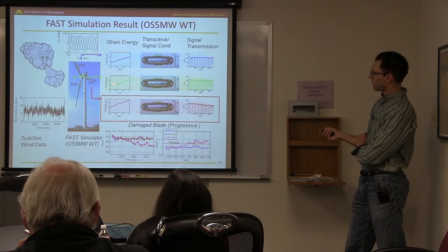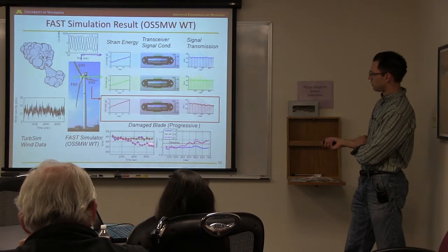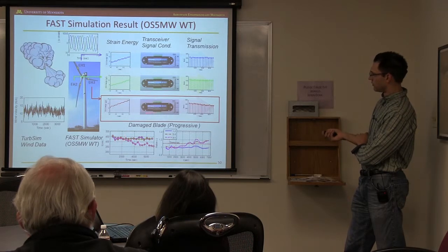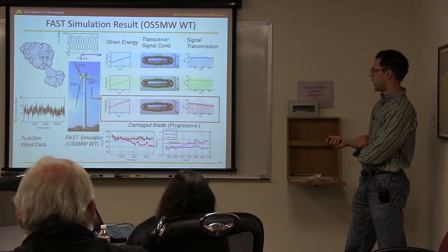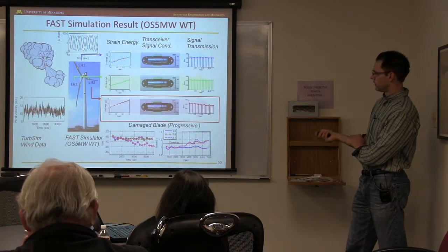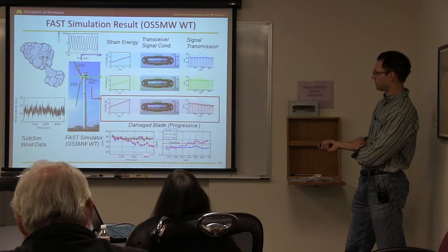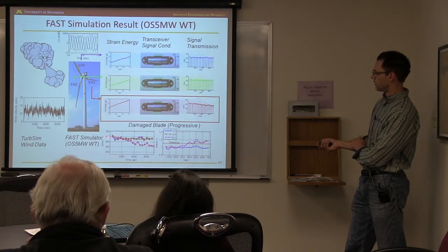And then once you've got the accumulated energy, as I mentioned, you get these pulses of data. And now if you compare the pulses of data, in this little simulation, 2 of the blades are healthy, one of them's got some damage. It's a crack, let's say, or a delamination in the blade. And you'll just start seeing its time to pulses start dropping off. This is happening on a much faster time scale than would actually happen in reality, just so we can run the simulations.